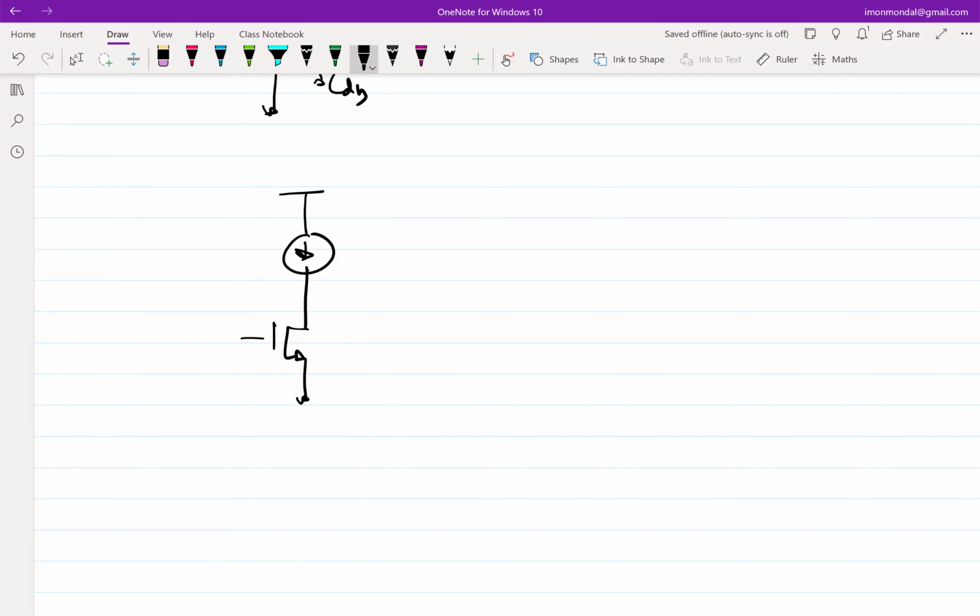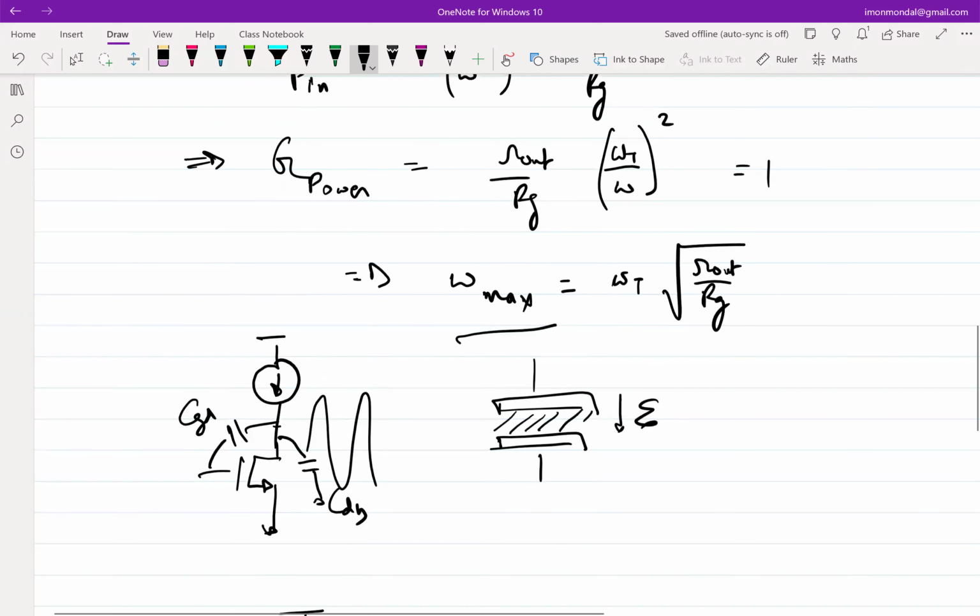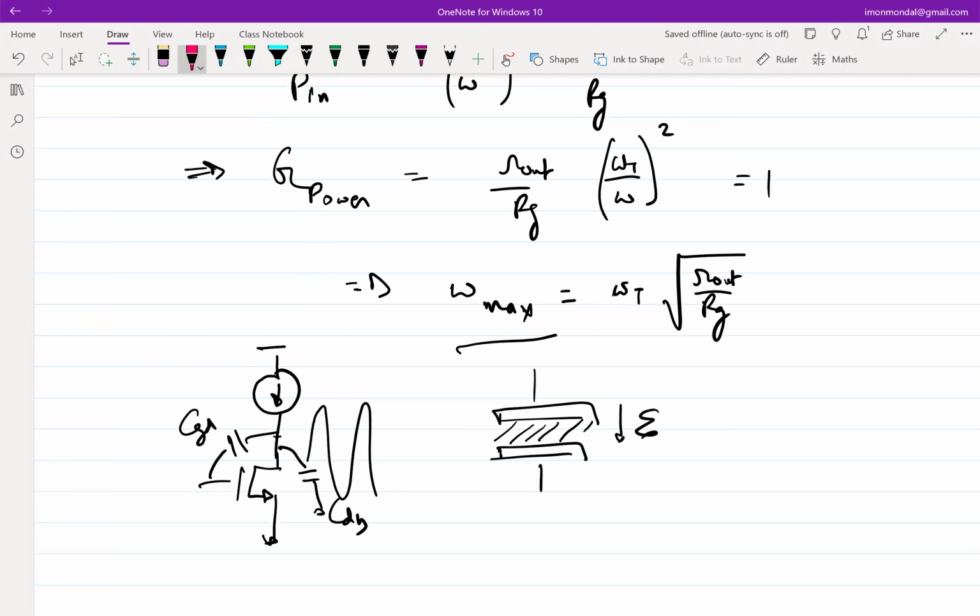Again, you should be slightly careful in taking that argument too far, because all of this assumes that the electric field in your capacitors is vertical. There are no fringe fields. This is correct if you have very tightly coupled metal plates.